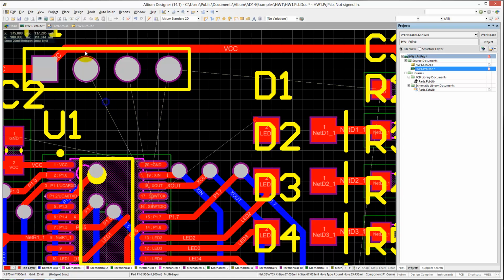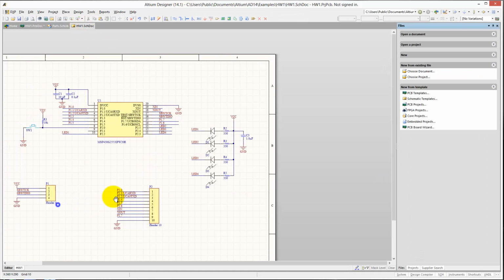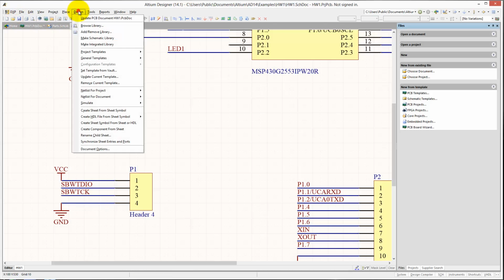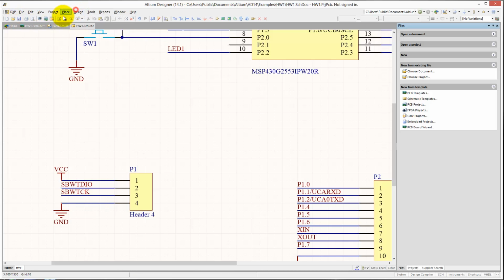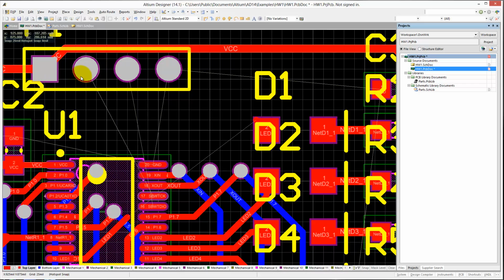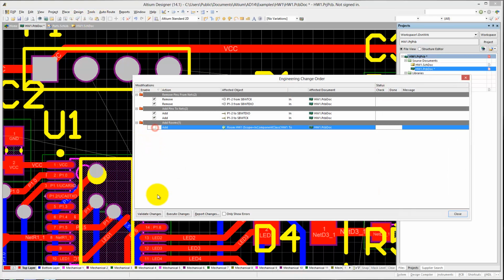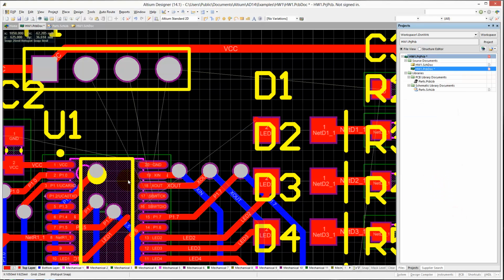So in this particular case, it's probably easier if we just go over here to these two signals and we just switch them around. We save it. This is not always possible. Sometimes a header, for example, is pretty fine, but in this case we will connect to these headers with wires so we can really do what we want and switch them around. We import them again. Remember to remove the room, and now the routing should be simple. We go from this guy here.